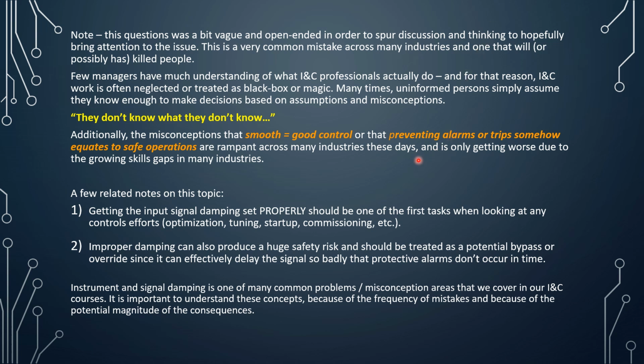The other misconceptions are smooth equals good control. A lot of operations persons have that in their head, and it is absolutely not the case. There's a lot of times you have to balance out smooth with fast, or else you're going to have cascading events and trips and other problems.